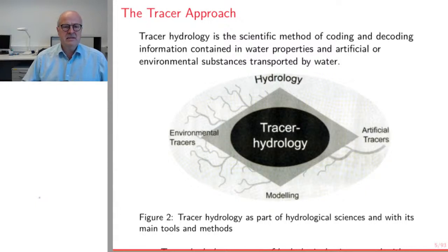This exercise is very applied and practical and important, because you can only carry out a tracer experiment if you have a permit and if this permit is approved. And on the other side, you need to know everything about artificial tracers to write a successful permit, which means you need to identify the tracer. We'll talk about this today. Choose the right tracer, justify why you choose it.